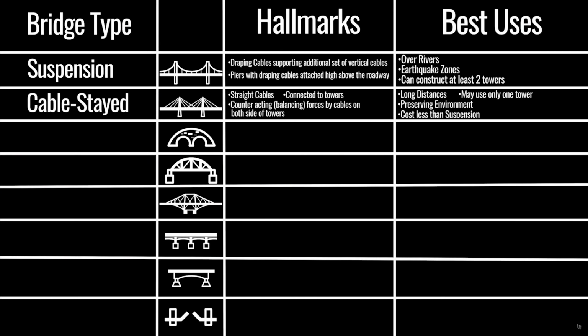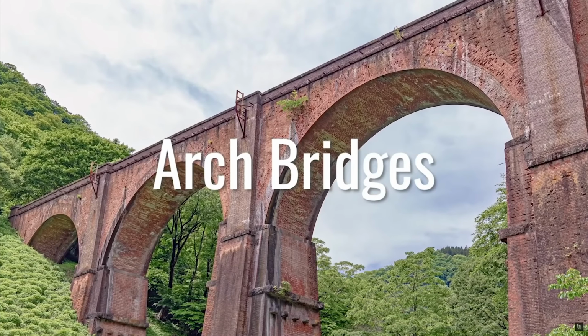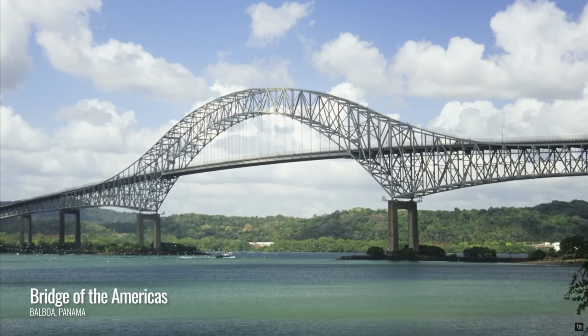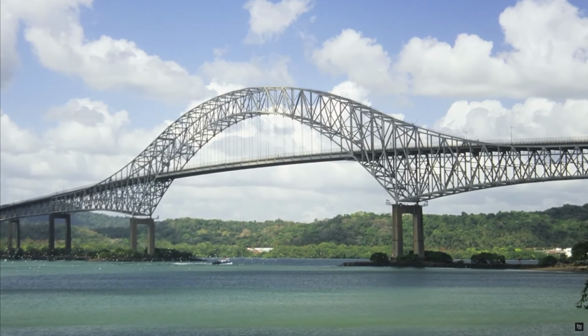What is our third bridge type? Arch bridges are primarily resisting the load in axial compression along the arc. Within arch bridges themselves, you could have a spandrel arch bridge where the deck is above the arch, or there are cases where the arch is elevated and the deck is actually through the arch. And so we call that a through arch bridge.